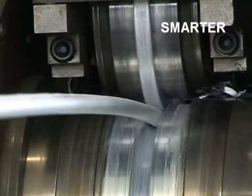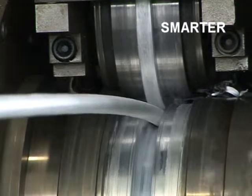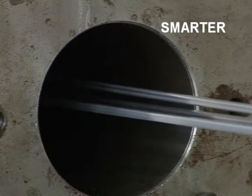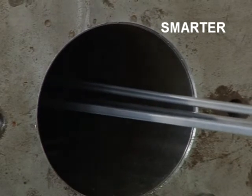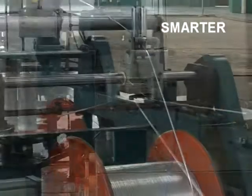The die holder is equipped with a fitting guiding board and a cavity, which an extrusion die is installed inside. The raw materials are compacted by the compact roller, then sent into the extrusion cavity to extrude it out of the die as products.